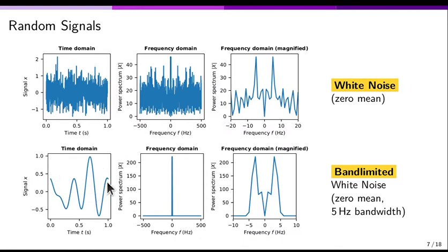If you take one of these signals and do the Fourier transform on it, you get basically 0 everywhere, and all of the power in the signal is sitting close to 0. If we zoom in on this little bit here, we get this graph. For a real valued time domain signal, when you do the Fourier transform, you get something where the power is symmetric. And so that's why it's got this nice symmetric shape.